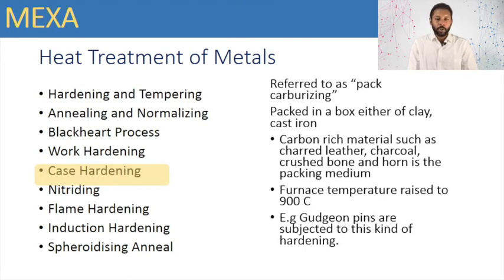The surface of the component will then absorb carbon, forming an extremely hard case. Gudgeon pins and other bearing pins are examples of components which may be case hardened. They would possess a hard outer case with good wear resistance and a relatively soft inner core which may retain the ductility and toughness necessary for such components.